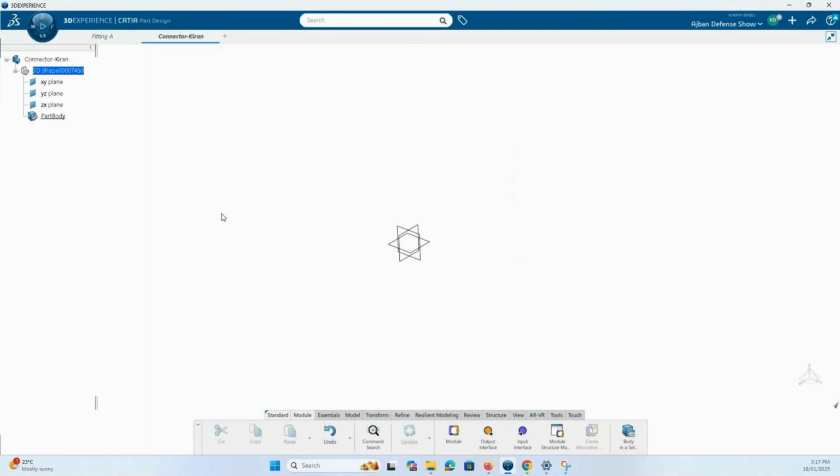So in order to do that, for me as a person, I like the environment to be a little more reactive, a little quicker, to my liking. What do I mean by that? When you start 3D Experience the first time you launch it, it's going to open in this environment which is for rendering. It's going to give you more shadows, a little bit of material finish and all that stuff. I don't truly need that because I need all the space, all the computation power, for helping me achieve the model faster.